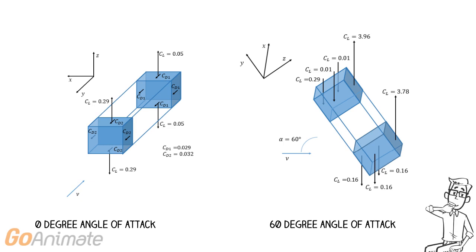For the 60-degree angle of attack, the lift coefficient was only positive on the positive z side of the kite. The remaining lift generated was in the negative direction. Nonetheless, the net lift generation is 7.23, a surprisingly large lift coefficient for the box kite at a 60-degree angle of attack. With the lift coefficient results from the simulation, it was found that net lift for the box kite at a 60-degree angle of attack and 10 meter per second wind is 411.4 newtons.